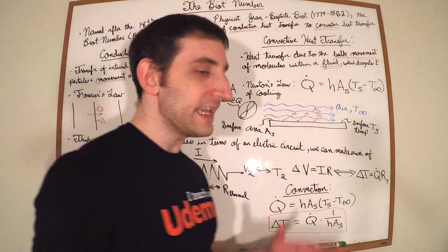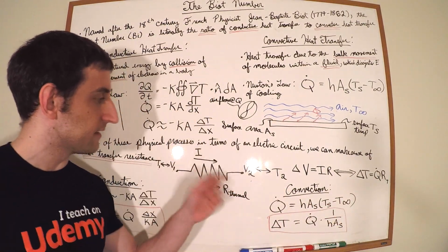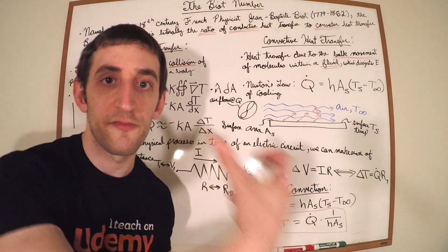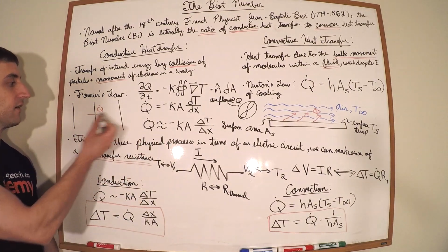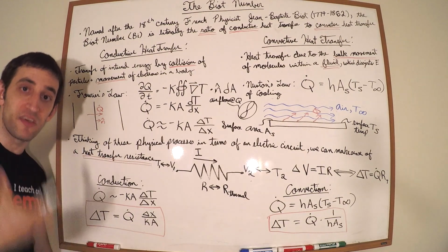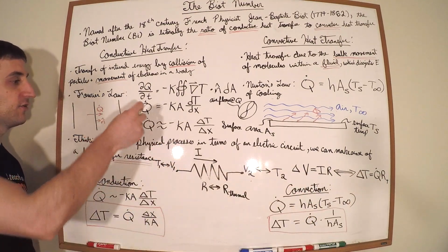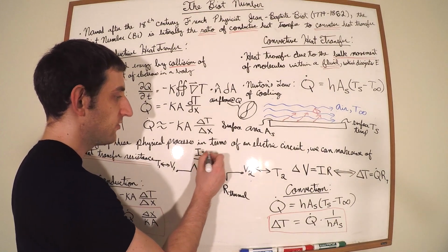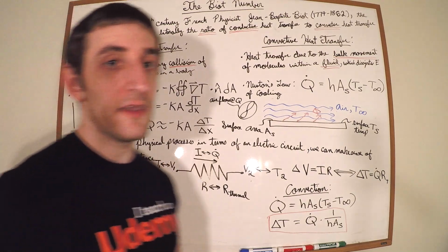So in electric circuits, when electrons flow due to that difference in potential, we say that there's some kind of current. The current is the flow of charge, okay? So in heat transfer, what we're talking about with that potential or that temperature gradient, we say that that creates heat transfer. The energy tends to move, and we measure the flow of that movement through this Q dot. So the heat transfer is sort of analogous to the current, and we can pair these two up here.